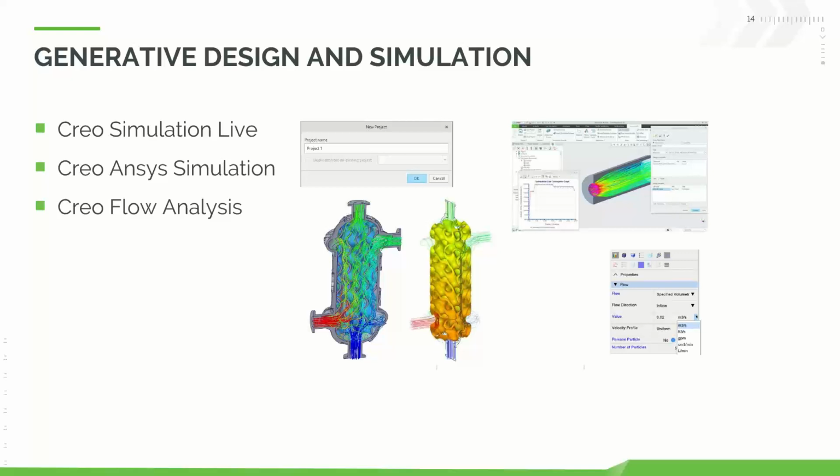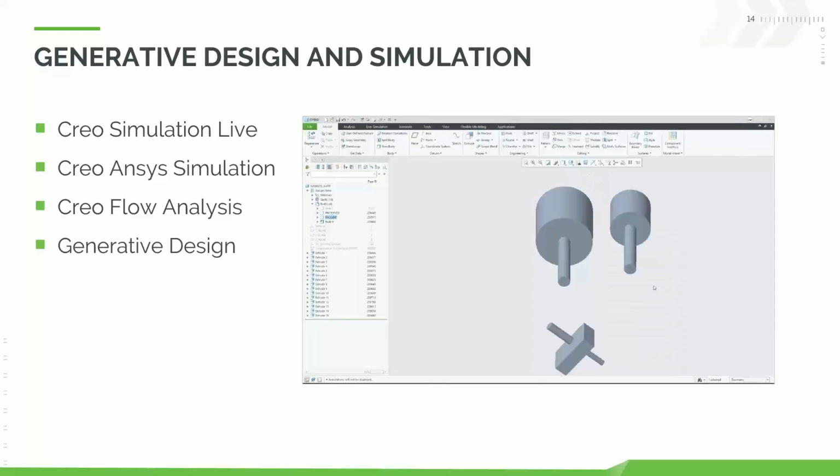A big one was the integration of behavior modeling into your flow analysis studies. This is a Creo parametric modeling tool that we've had for a while, and it's something that we use for setting up different goals and being able to let the system automatically solve for different parameters based on that goal. And this is something that now works very well in flow analysis. For example, if you wanted to solve for a certain exit velocity based on 3 or 4 parameters that you can change, we just let the system know what that is. It runs and goes and finds the optimal values. It sees what the effects of that are and sees if we can do an optimization for that given goal. And that's all something that can be done within flow analysis now. So some definite enhancements in that sense.